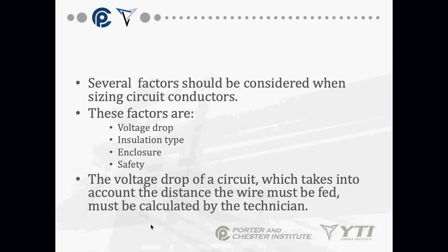Anytime wire calculations come up, I just let the electrician do it. But you do have to realize that there is voltage drop. The longer the wire, the larger the voltage drop is, and believe it or not, it can actually take you under the required voltage of the system if it's not sized properly. Why doesn't everybody put in large wires? Because it's more expensive, so a lot of times contractors try to put in the smallest wire they can possibly get away with.